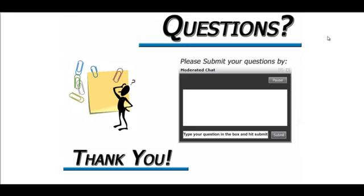Okay. The next question, and I'll again direct it to both of you. Are there condensation issues or challenges in the mixing box when the delta is high? Okay, so the delta T between the hot air coming back from the return versus the cool air coming in when we're mixing, there are some condensation issues, and in my drawings we did not deal with humidity issues.